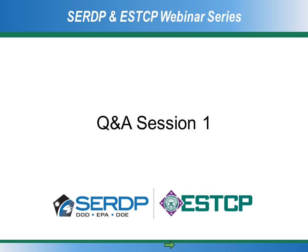So we've had the discussion that maybe a new ESTCP project would be to go out to a site with a handful of different dyes where you have a release of mixed DNAPL, and use the different dyes in combinations to delineate where you have different types and different releases of different DNAPLs in the subsurface. So I think it's really just the beginning of an exciting time of enhanced forensic analyses using dyes in combination with laser-induced fluorescence to do a much better job of delineating the nature, extent, type, and saturation of residual DNAPL and LNAPL in the subsurface.